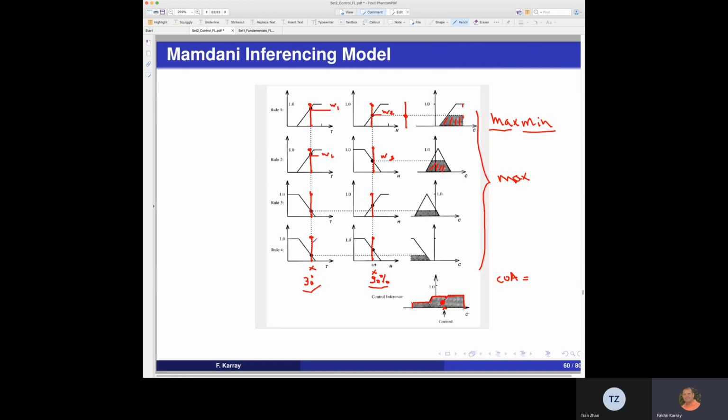And that's why we showcase here the fuzzification part, as I mentioned to you. So this is the fuzzification part here, the fuzzification by singleton fuzzifier, and then aggregate. Okay, so after the fuzzification, then we look at the minimum, so the firing strength, the clipped version, and then we aggregate all the values of the clips to find the maximum of the membership function.